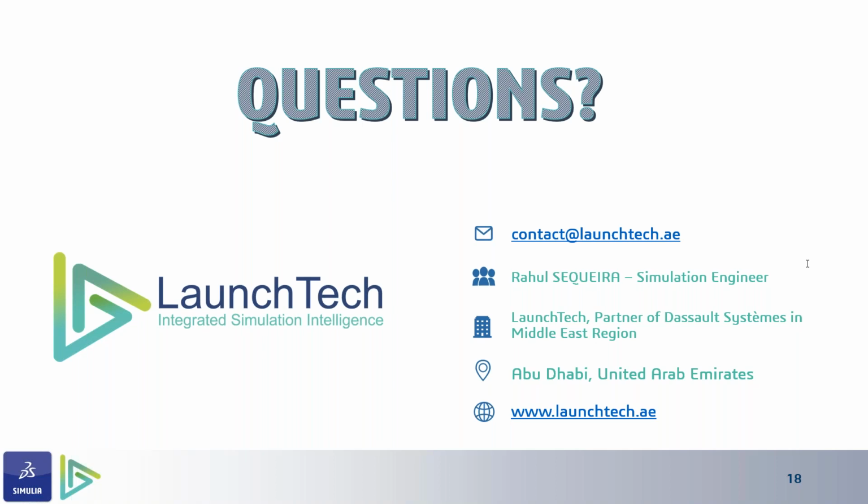Another question I have is, what do I think is the best material model for, let's take an example, 304 stainless steel? Well, it depends on the application again. If you think about NVH, the noise, vibration, and harshness applications used in automotives, then yes, I think the Young's modulus and the Poisson's ratio are more than enough.